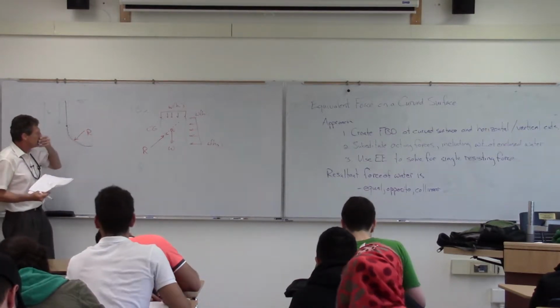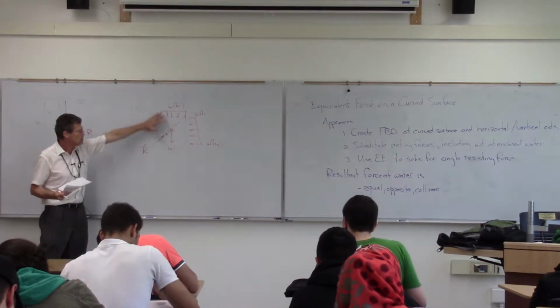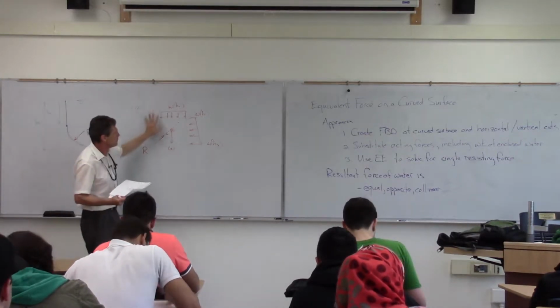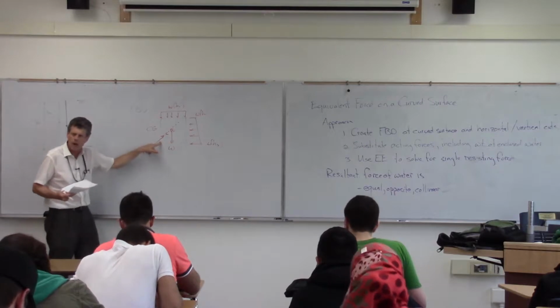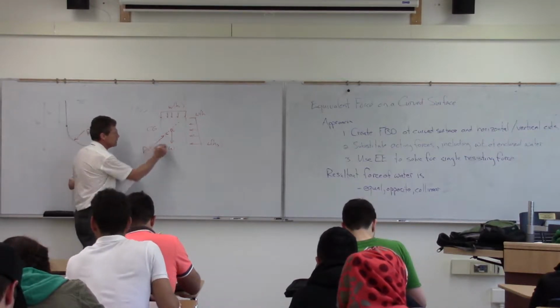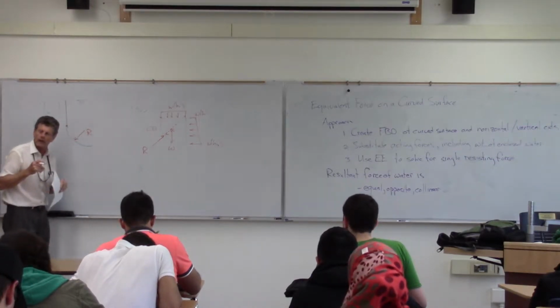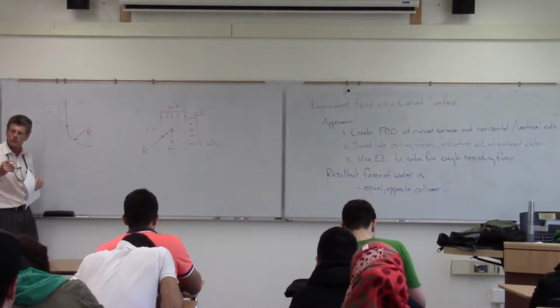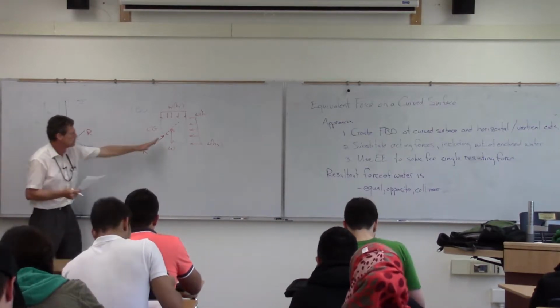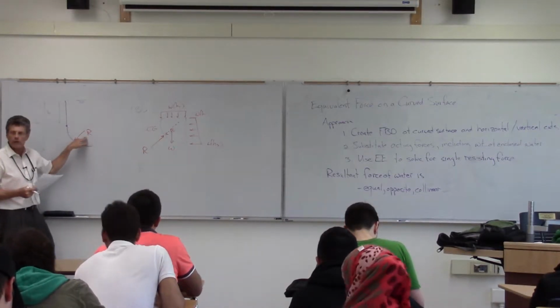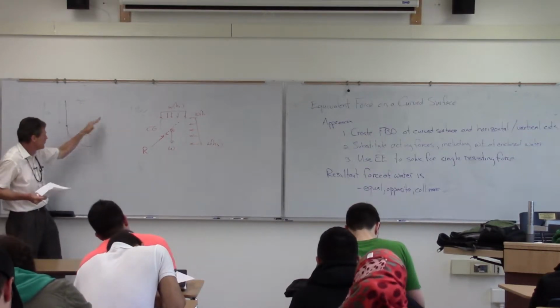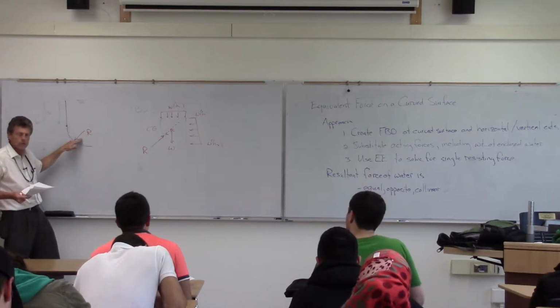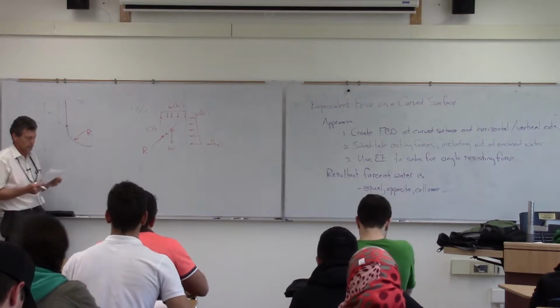So it isn't as complicated as it looks there. It's just that you're going to have to keep all of these pieces together. Probably the most complicated part of that particular approach is just finding that single resultant force. What we want to do is find that single resultant force, realize that if it's a two-force system, then the water will be acting in the opposite sense there, but equal, opposite, and collinear.